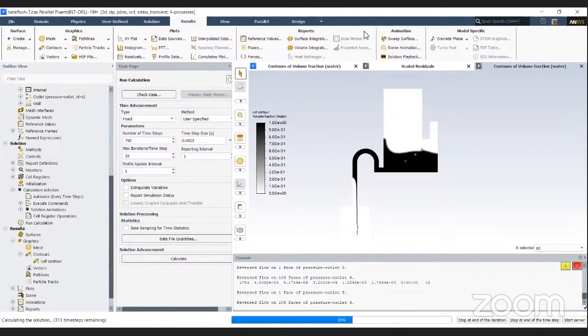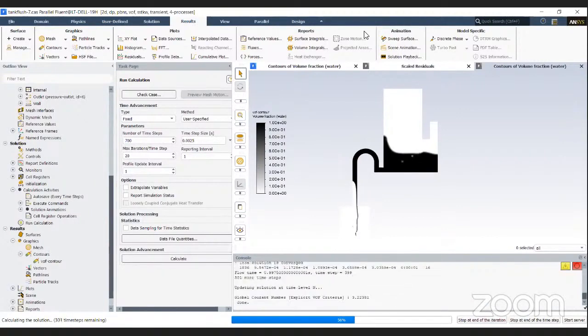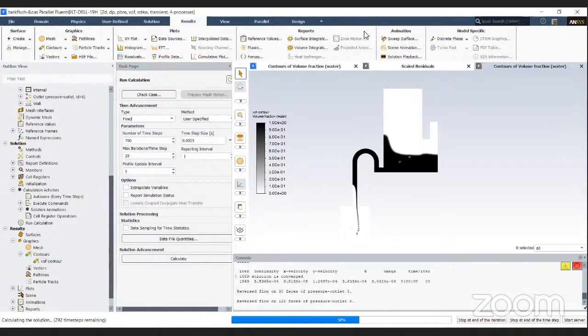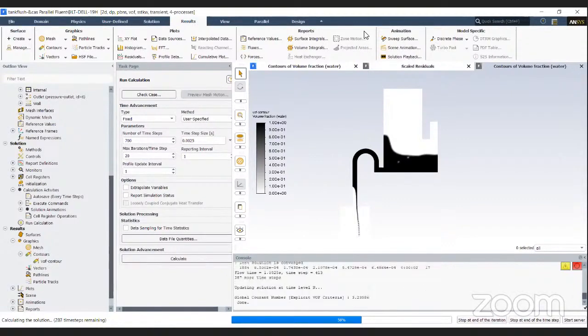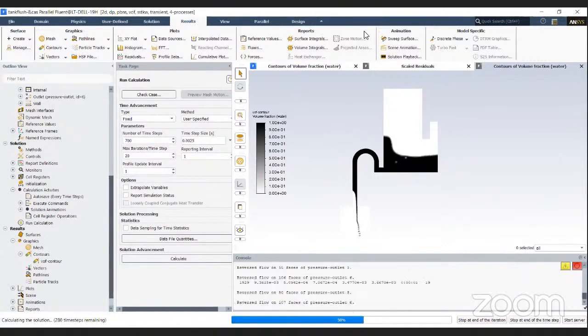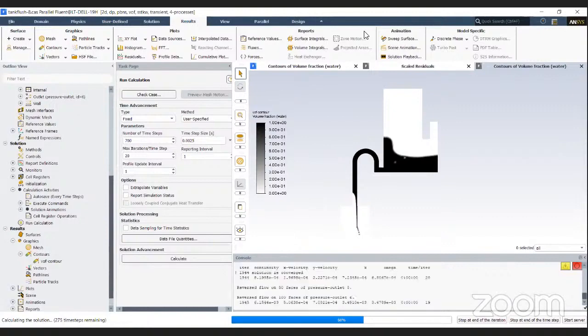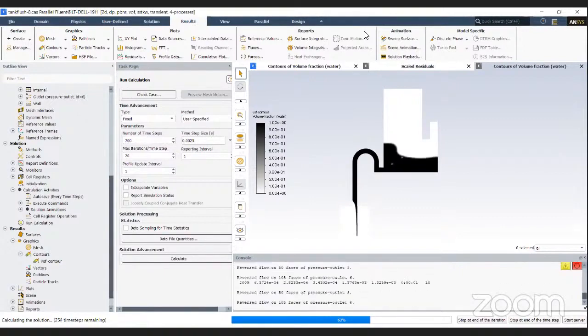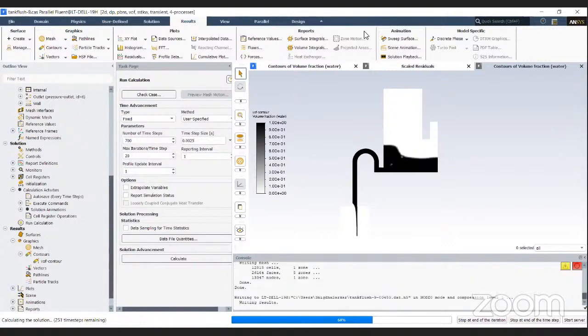So there are different cases in which you see more than one phenomenon, or when you have these different types of secondary phases dispersed in your primary phase. There are different ways of going about it. Some of the models take into account everything. For example, the Eulerian model that I was talking about earlier, because it solves individual equations for all the different phases, it can be really accurate, but also time consuming at the same time, wherein it'll be able to capture all these individual phenomena correctly.